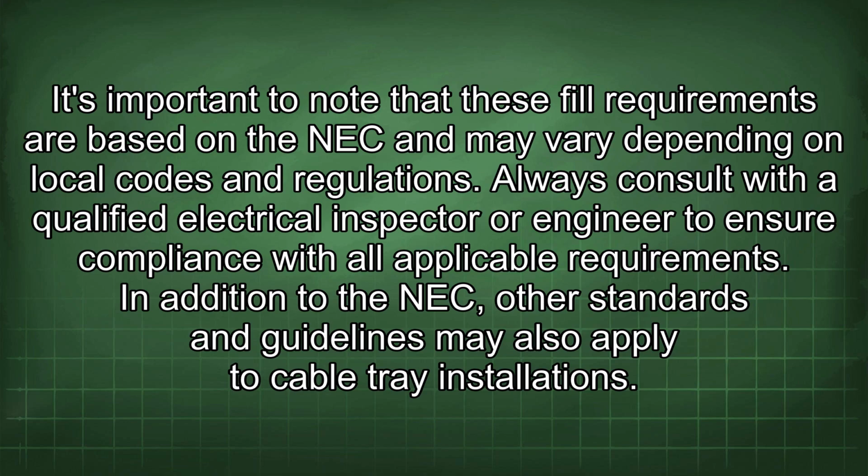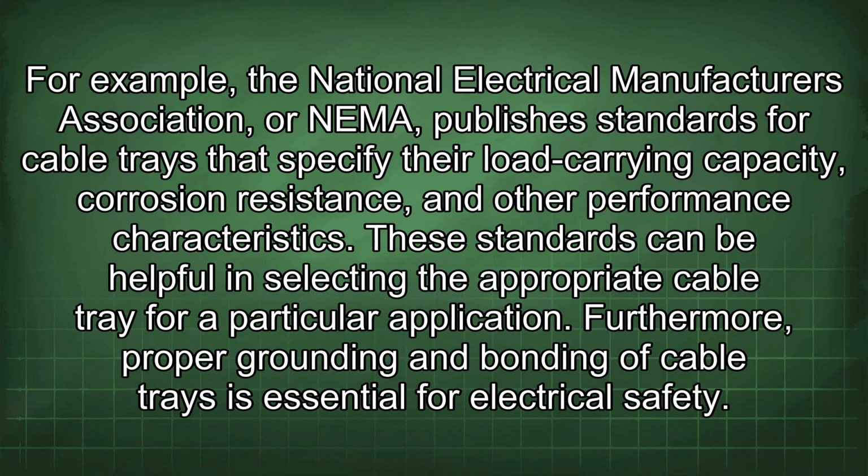In addition to the NEC, other standards and guidelines may also apply to cable tray installations. For example, the National Electrical Manufacturers Association, or NEMA, publishes standards for cable trays that specify their load carrying capacity, corrosion resistance, and other performance characteristics. These standards can be helpful in selecting the appropriate cable tray for a particular application.